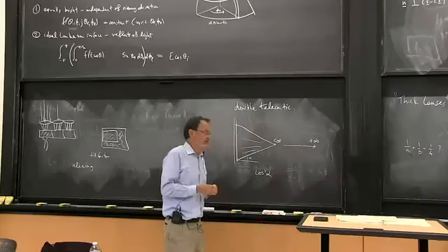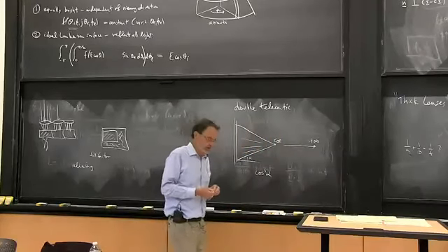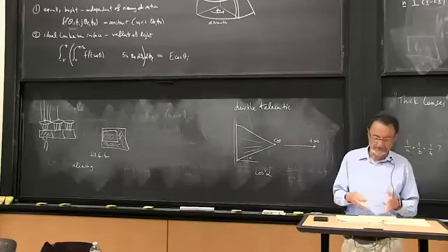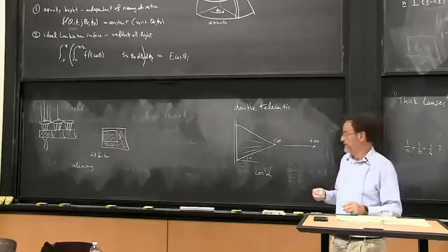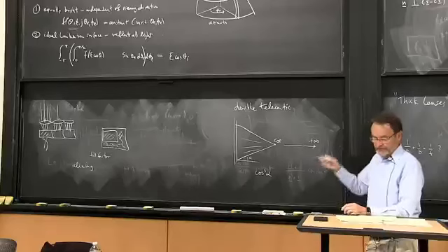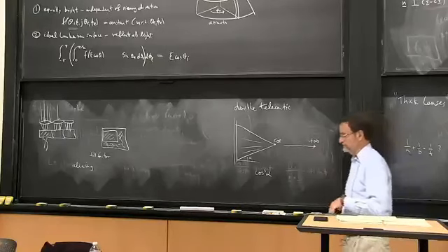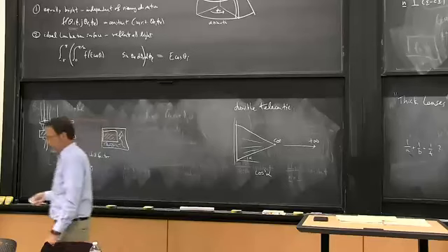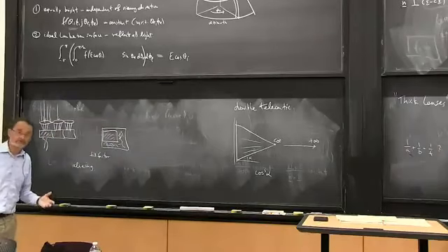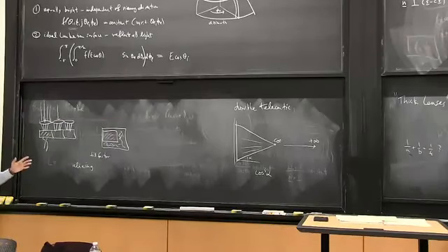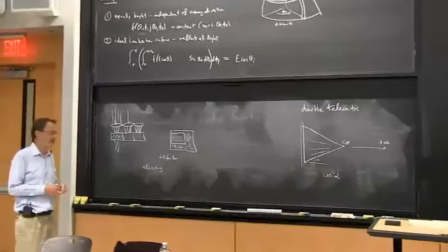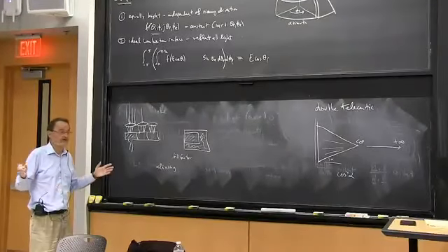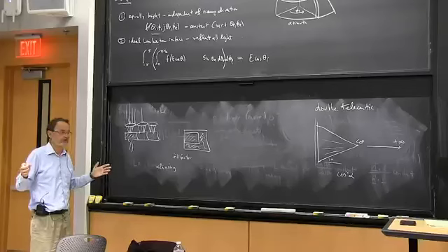And those will create effects where some high-frequency component looks like a low-frequency component, aliased down to a lower frequency. And how do you avoid that? Well, you low-pass filter first. And then there's a wonderful theorem that says if you have a low-pass signal, you only need to sample it at twice the bandwidth of the signal, and you can reconstruct it perfectly.